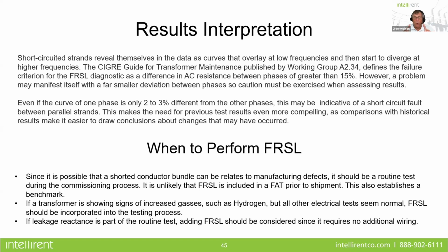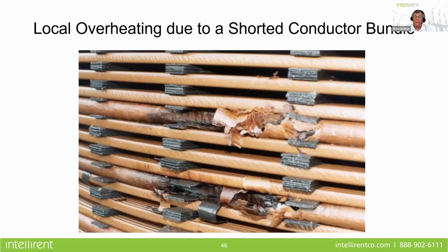Because I'll tell you this right now, there is no other diagnostic test available that can find this condition until it gets too late. And when it gets too late, this is what you're going to find. Overheating and eventual insulation failure due to a shorted conductor bundle. So that's just a little added bonus that I thought I'd throw in.